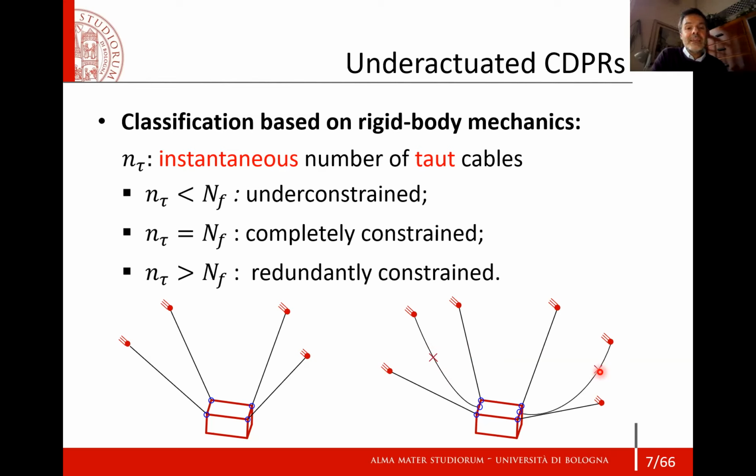So they do not set any kinematic constraint and they do not even set a static range constraint on the platform. So even if the number of available cables in both cases is different, these two systems behave in the same way. And any cable can become instantaneously slack, even if their number is 4, 6, 7, or 8. And the problem of slackness, I'm sure you are very aware of this problem, whichever is your background.